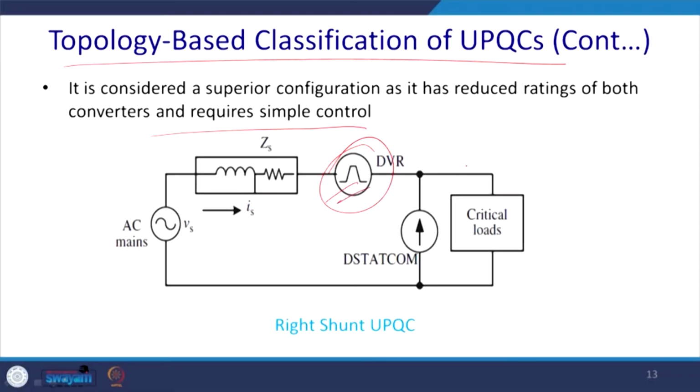You already have a quality voltage source, so for unity power factor, you can generate the unit template and do the compensation. And if there is a swell, it has been mitigated, so the ratings of these devices are less, and it is a healthy, notch free supply with no disturbance from the voltage side. But ultimately the DVR takes the brunt.